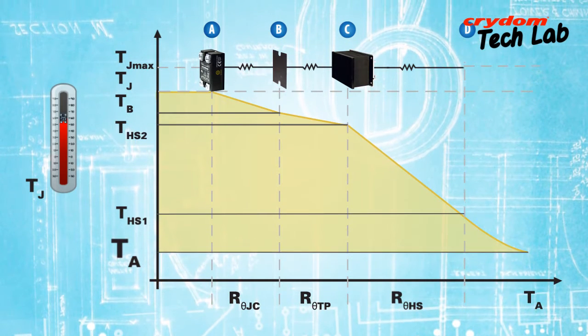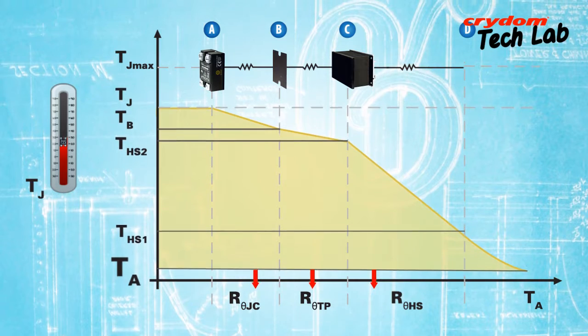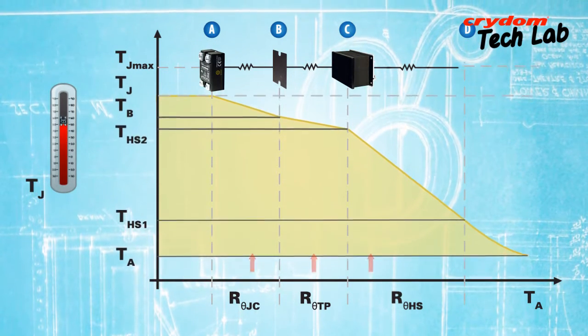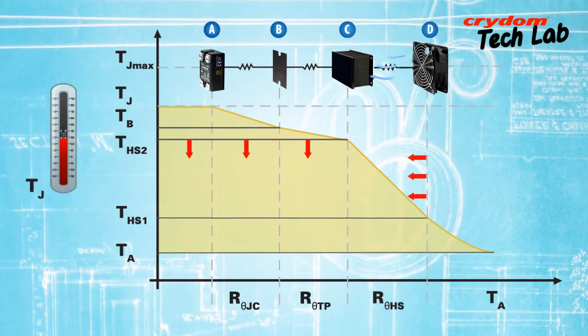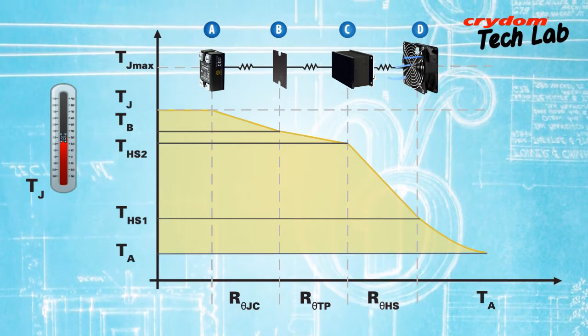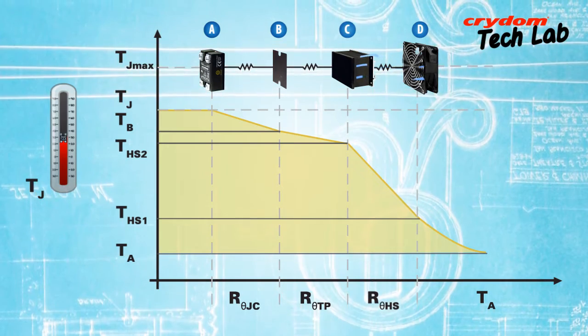The ambient temperature acts directly on the relay's temperature, increasing and decreasing it in direct proportion to the surrounding ambient air temperature change. Forced air flowing over the heatsink effectively decreases the heatsink's impedance, thus reducing the relay's temperature. Forced airflow over a heatsink is the subject of another TechLab video.